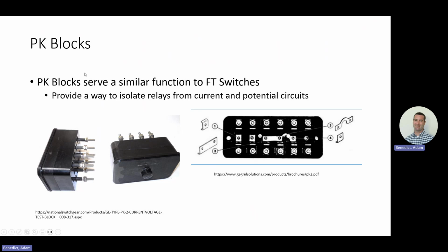So PK blocks, I've seen this mostly again on high impedance diff, where you would pull this block out and all at once you would short or open all the circuits connected to this block. So this just yanks right out. And it's not easy to pull out. You have to intentionally pull it out.